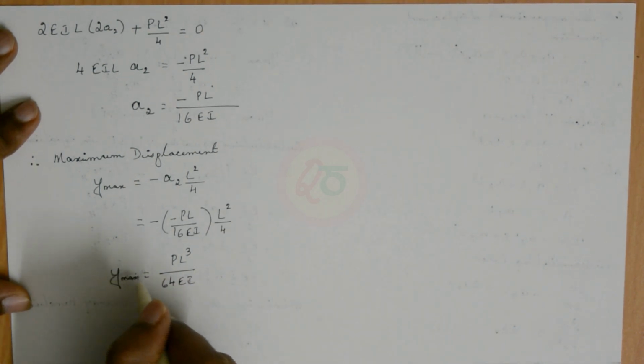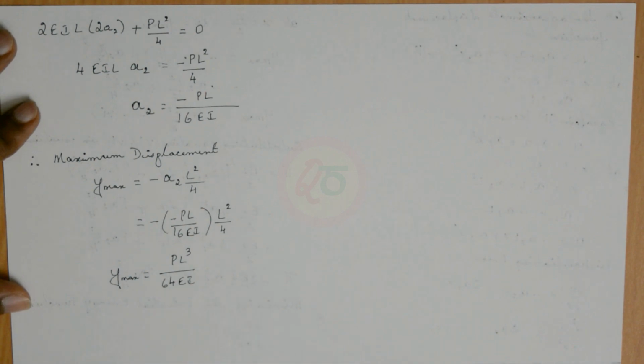If you observe, this is far off from the exact solution. Hence, for a beam, assuming trigonometric displacement functions yields better results. Thank you for watching. The next sessions will take up one more problem on simply supported beam, and then we'll move on to cantilever beam. Thank you.